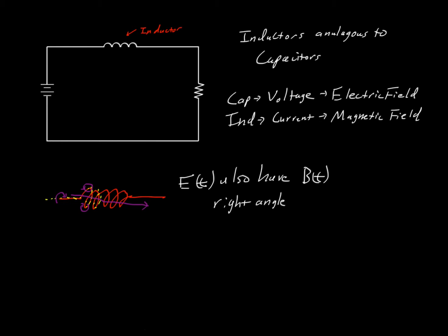So, how does that affect our actual circuitry? Well, what it does is it causes, let's say, current over time. So let's start at zero current, and let's close the switch on this circuit and start the current flow. Without an inductor, it would pretty much jump instantaneously up to whatever the current flow was dictated by the resistance of the circuit.